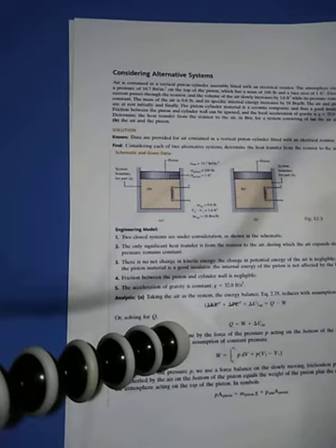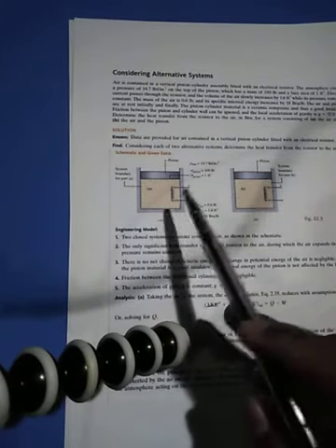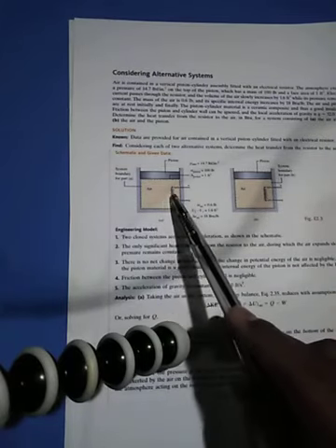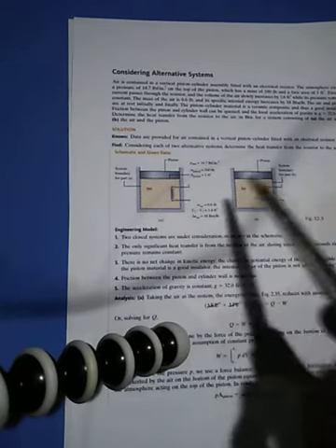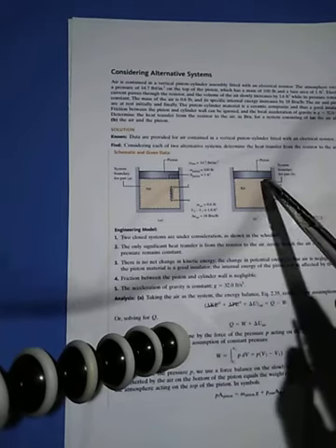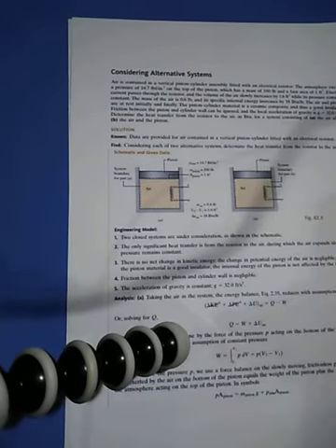The first model is two closed systems are under consideration as shown in the schematic, no? So the first system is the air itself. Okay, air lang, so hindi kasali yung whole system. So the second system is air including the piston, no? So lahat. Okay, so number 2, the only significant heat transfer is from the resistor to air, during which the air expands slowly and the pressure remains constant.